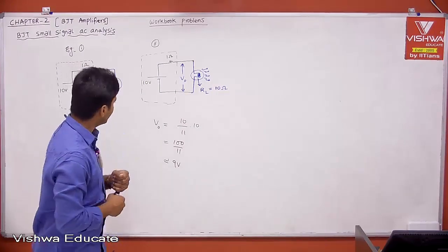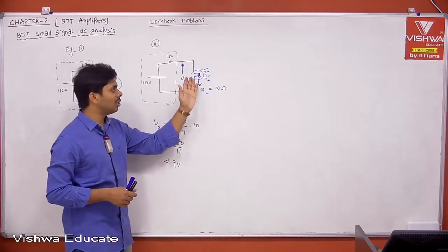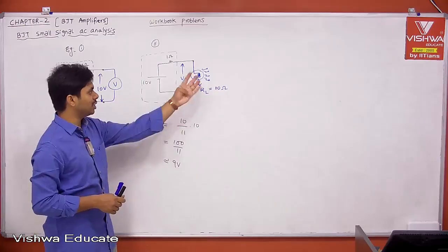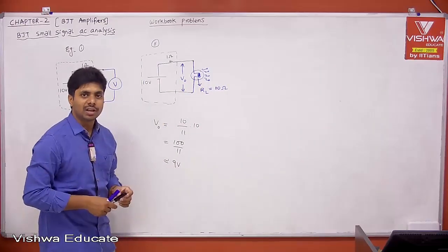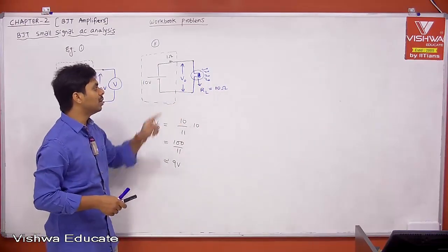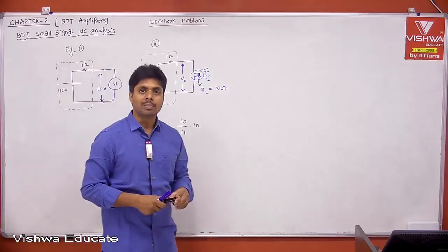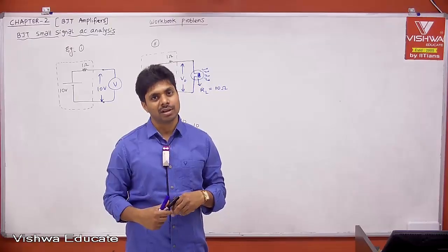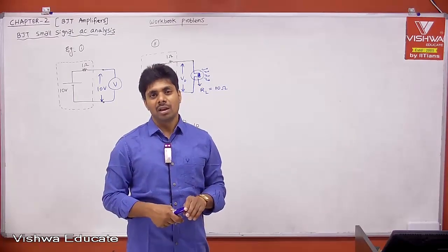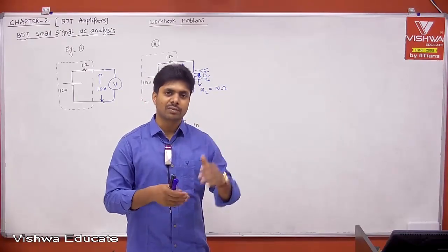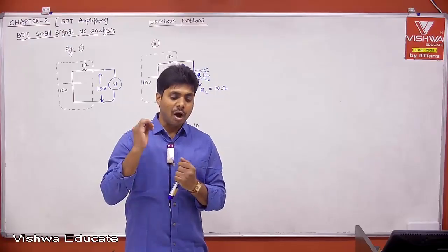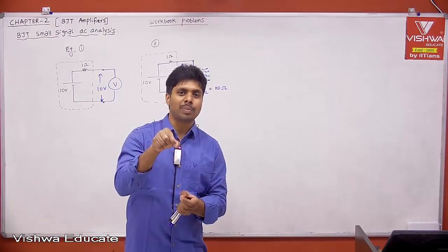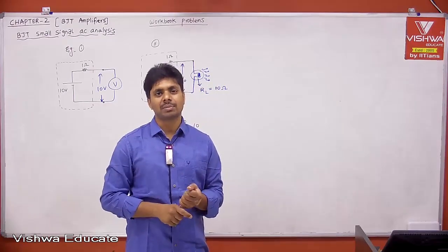Now, here, if you connect an actual load, your V0 became 9. And let me tell you, if you change the load, your V0 will also change. Therefore, this is a load-dependent voltage you are getting at the output because it is a practical voltage source. That is your practical voltage source, which is not acceptable. If you want a constant voltage for any circuit, and the voltage you are applying to the load is different when the load is different, that is not acceptable.